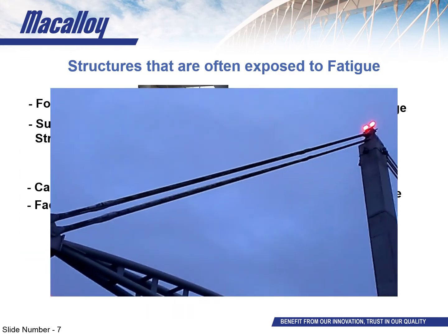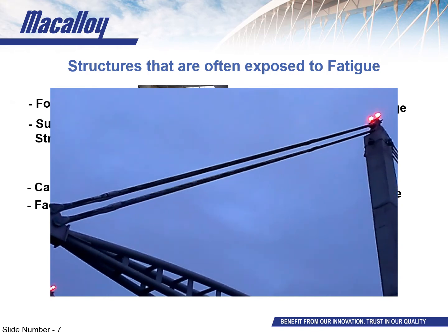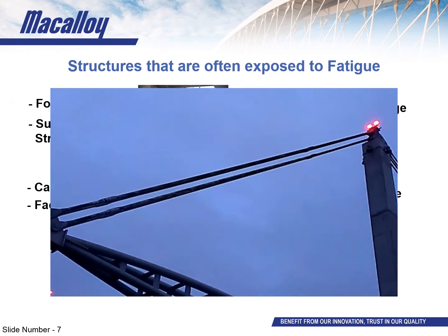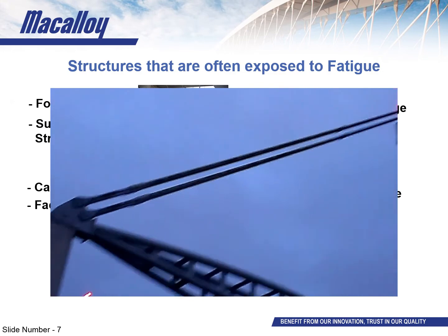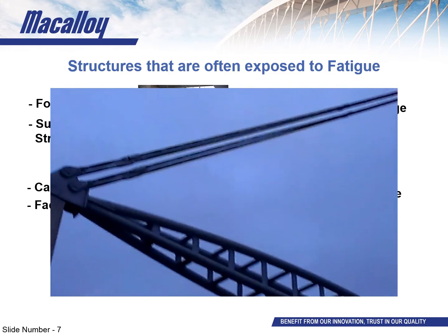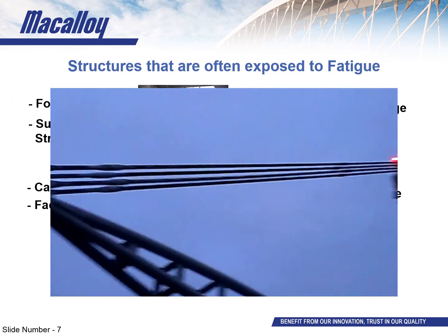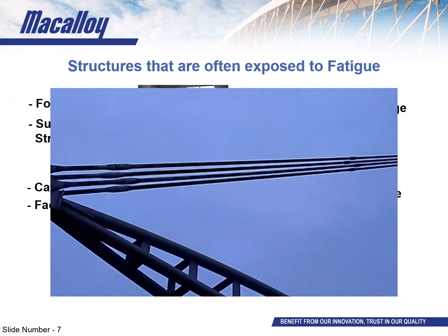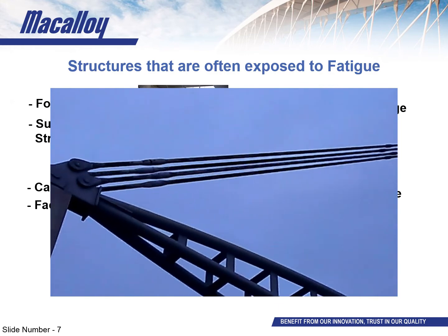Now, we did actually experience this in a project in the Czech Republic where the design of the surrounding structure, along with some inconsistent preloading by the contractor, resulted in the bars themselves experiencing resonance. So one of the bars had a slightly different level of tension in it than the rest. Now, this altered its natural frequency, and it lined up its natural frequency with the fatigue loading that it was subjected to. This hanger itself oscillated quite violently, and that resulted in a fatigue failure in the bar itself.